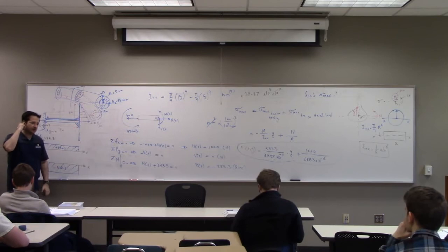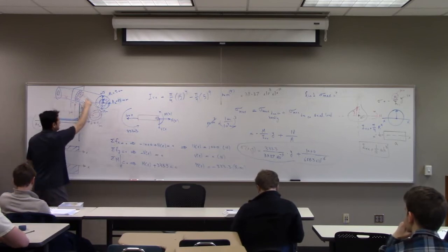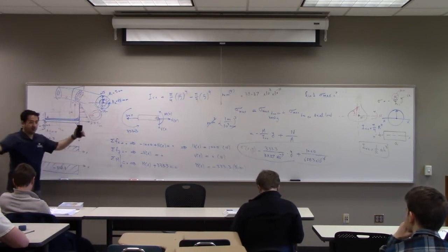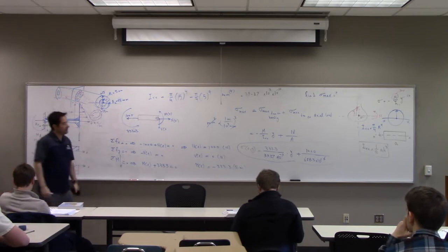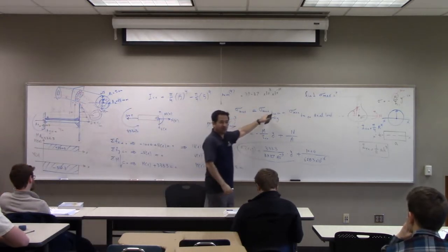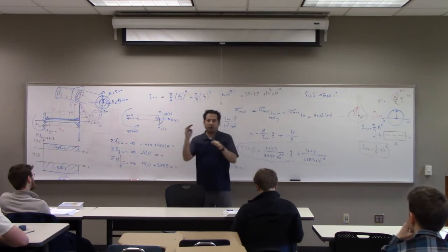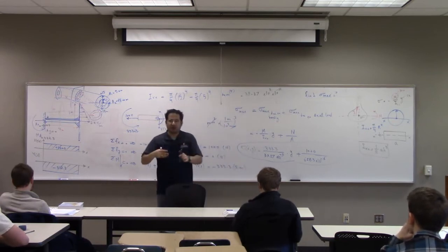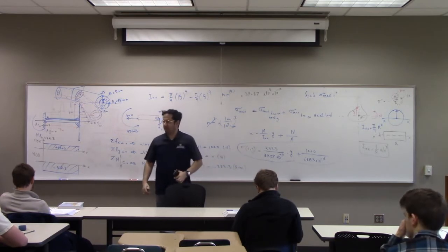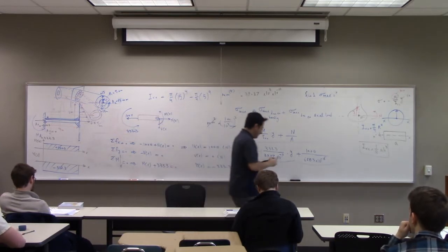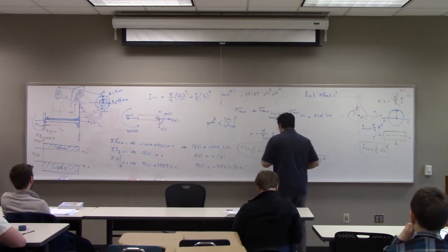And then you may get confused and say, well, if I have a stretching and compression, shouldn't it be equal like the way we did before where we had pure moment? Because you have axial load. And because of the principle of superposition, this comes from exactly superposition. So I consider only the bending effect, and then I consider only the axial effect. And then I sum them together. Right? Another problem.